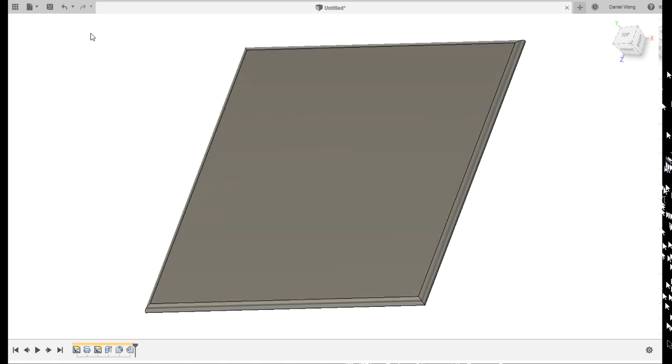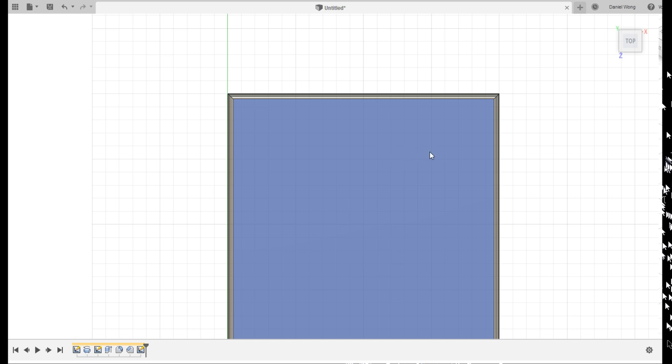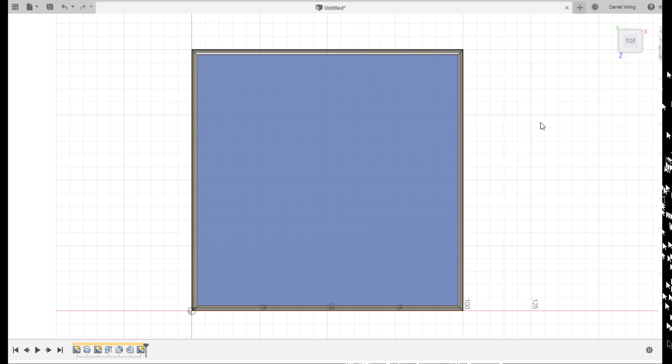The way we're going to do that is I'm going to create a sketch on the top surface, and the top, by the way, is the top with the fillet, in case you're wondering. You'll notice that when you draw a sketch, it automatically creates a boundary on any surface that contacts that sketch plane. Here we had a square, and because I drew on the square, it automatically gives me the square as sketch geometry. You guys can see that, right? And it automatically converts it for you.